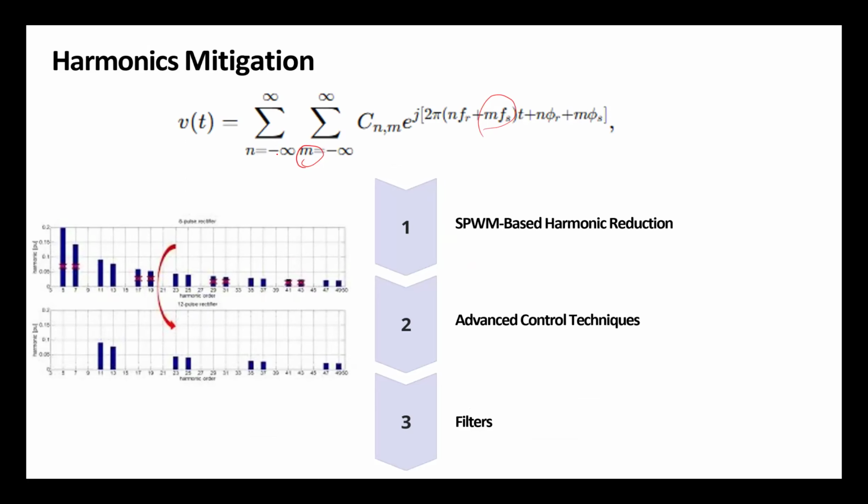If we have a low pass filter, one way to eliminate the harmonics is to push all the harmonics to a much higher frequency, so the filter will just lower them. So we push them toward the high frequency, because we all know there is a filter out there that would get rid of them. This is one strategy.